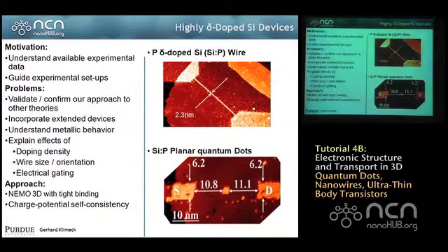And they can pattern these sheets, right? They can make big pads, then they can make a thin wire around it and then connect to a big pad. And they can actually measure current flow through these structures. And these wires are as thin as 2.3 nanometers. That's 4 atoms wide, 1 atom thick. Okay? If you talk about the ultimate limit of nanoelectronics, that would be it. Okay? That's really small.